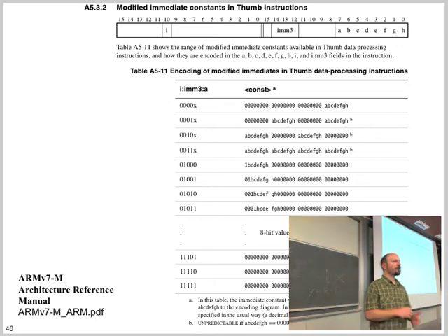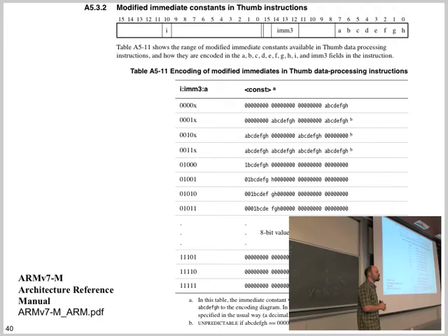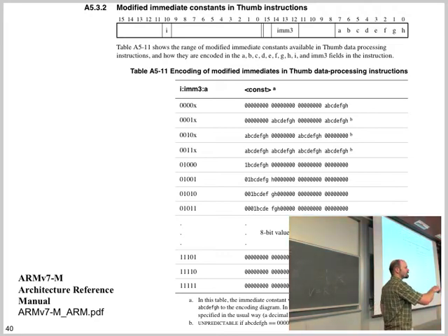Any questions so far on opcodes and decoding and encoding? No? Yeah? Please ask questions. I mean, now is the time. So for the processor to know if it's doing a 16 or a 32, is that in the upper 15? Yes. Some of it. There are a couple of keywords up in here that will tell you if it's a 16 or a 32-bit operation. Yes. And that way it knows, is it 2 operations or is it 1 opcode that I have to decode?